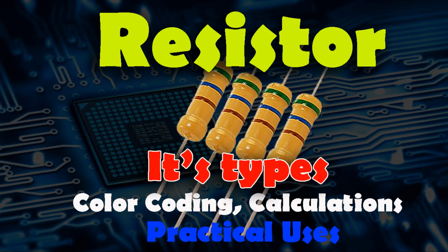Formula. The power dissipated as heat in a resistor can be calculated using P equals I squared R equals V squared over R, where P is the power dissipated in watts, I is the current through the resistor in amperes, R is the resistance in ohms, V is the voltage across the resistor in volts. Example: in a resistor carrying 2 A of current with a resistance of 5 ohms, the heat generated is P equals 2 squared times 5 Ω equals 20 W.